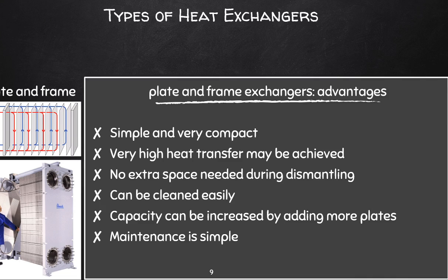So we are doing all of these exercises for internal and external flow over flat plates and all of that. Well, this is where it comes into play in the design of these heat exchangers. The heat transfer coefficients, which you should now know how to determine for flat plates, are generally higher than for the shell and tube heat exchangers. And the cost of the metal per surface area will also be much less than for the tubing.